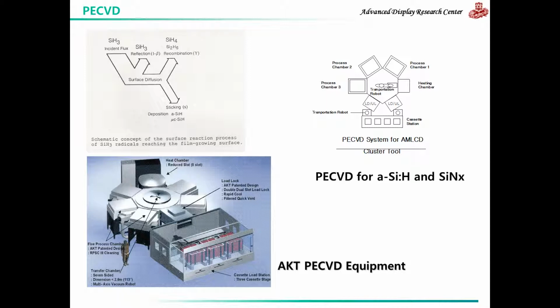This example is from Applied Materials and it consists of a multi-chamber cluster deposition system as schematized by the diagram at the top right corner here. The advantage of this system is that it allows the consecutive deposition of more than one TFT layer without breaking vacuum, leading to very clean interfaces.